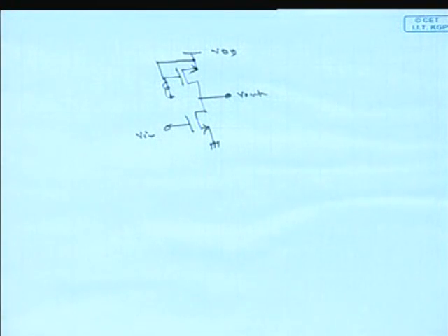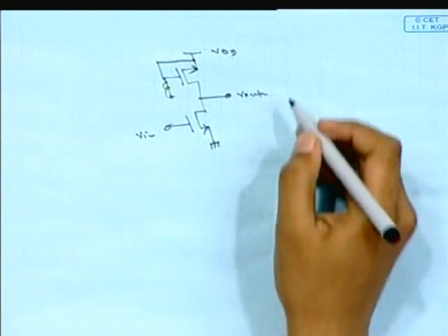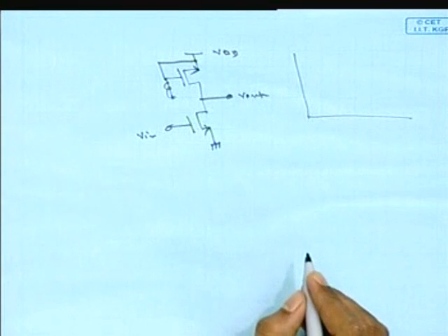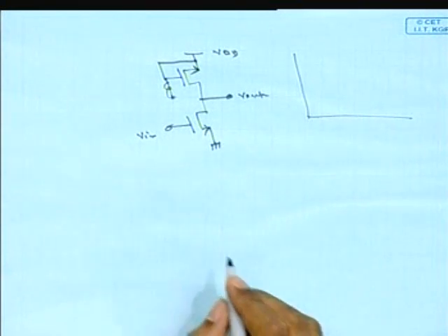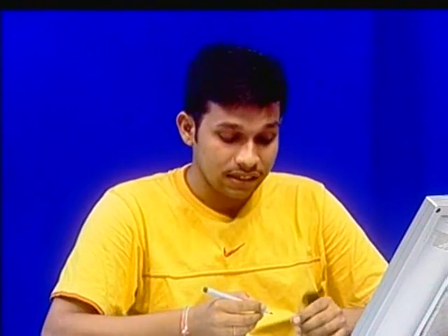This is the diode connected load CS stage. Firstly, we directly go to the DC analysis of this particular stage. We see that whenever this Vin is less than Vth, the lower transistor will be off. But what will be the output voltage then? It is not a passive resistor, that is RD. It is an active resistor. We are saying this is an active resistor because we are using an active device. So it is called the active resistor, and as it is a diode connected load,